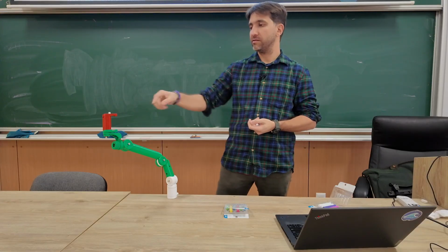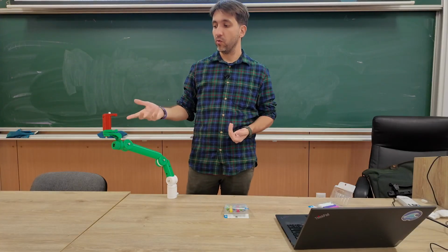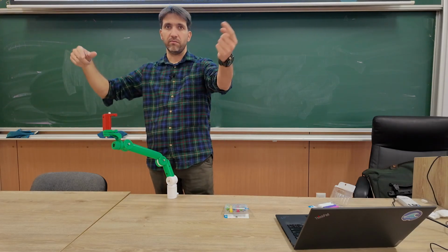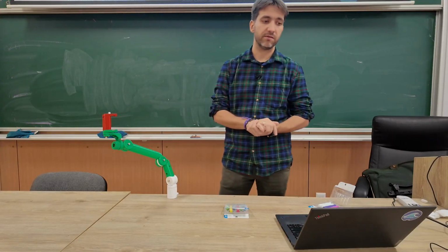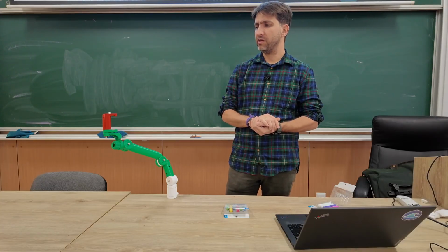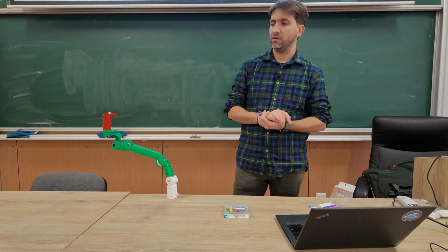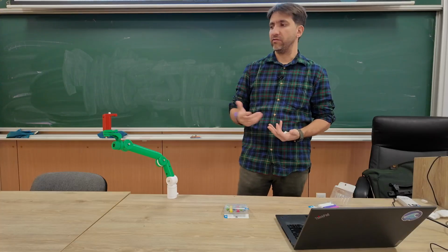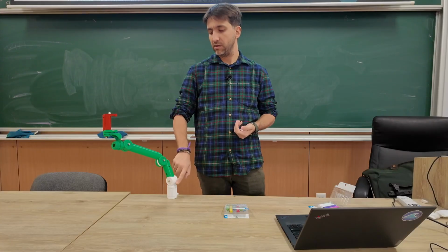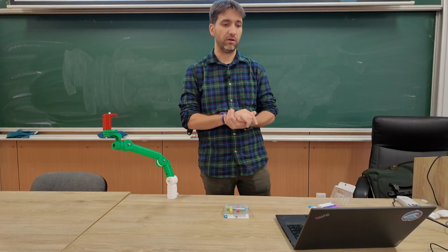All right. So you're saying that controlling the end effector directly, having the response be the end effector and the set point be the end effector pose, would be complicated. Why? Because we cannot measure it directly. I mean, we can if we have an external system with cameras or whatnot. Yes, sure. So that's one part of the problem. The other part of the problem is, I cannot measure the end effector pose directly. Can I control the end effector pose directly? No, we also need to control the base with the joints. We need to actually control the joint coordinates so that I end up having an end effector position.